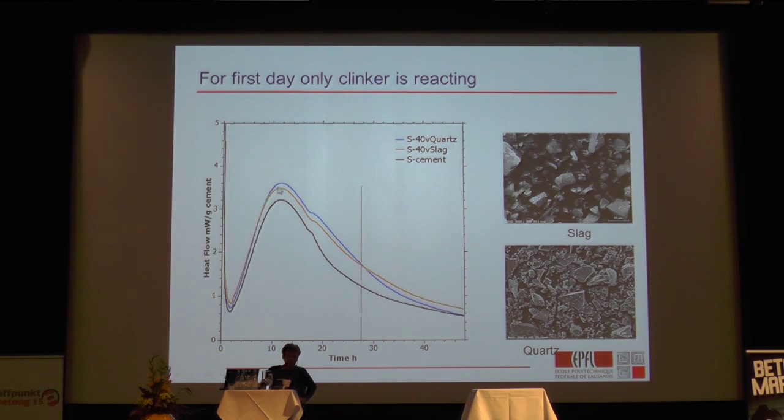But what you see here is for the first 24 hours or so, whether we put in quartz or whether we put in slag, it's exactly the same story. Quartz is obviously inert, it's just the physical presence of these particles which slightly enhances the reaction of the clinker component. And only after the first day or so do we start to see a slightly higher heat here from the slag, because now the slag's starting to react.